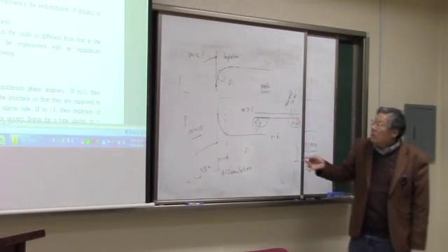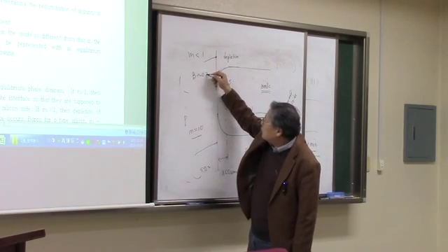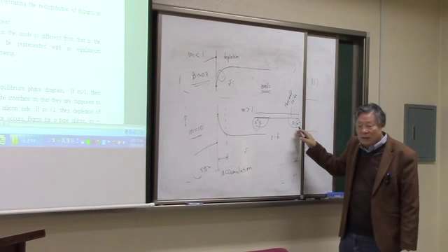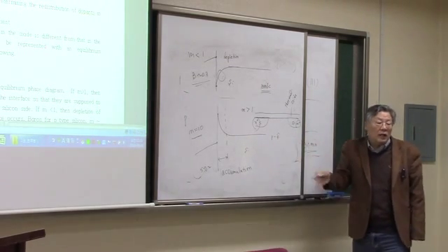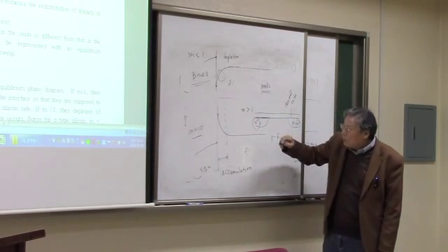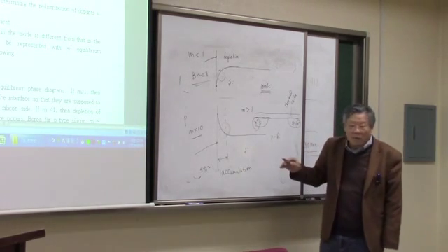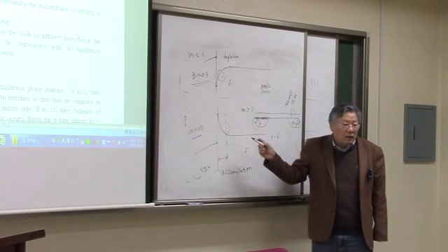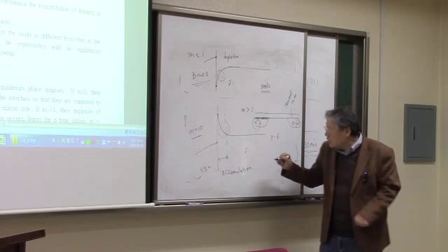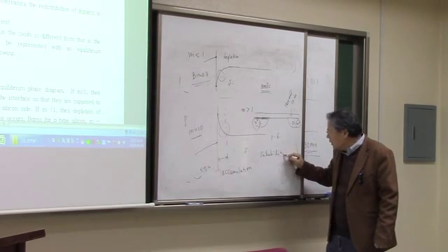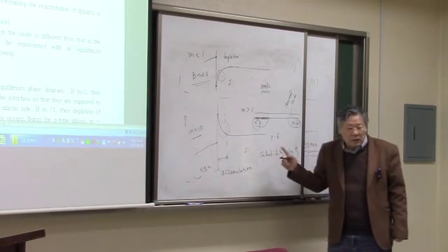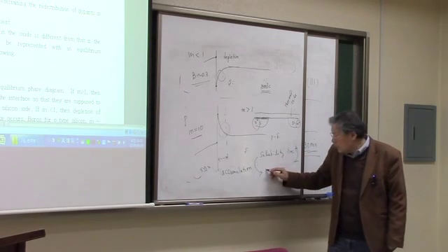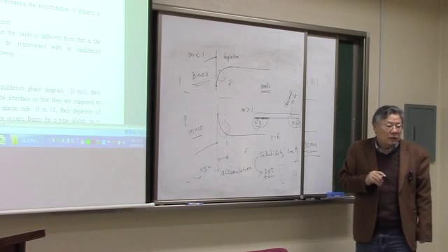It's much greater than 1. In the boron case, the M value is about 0.3. It's less than 1. So if you have a phosphorus doped area like this, locally, and then you grow thermal oxide in a later process, then at this interface you're going to have accumulation of the phosphorus at the silicon interface, right? What happens if you have an accumulation like this? Then this accumulation may exceed the solubility limit of phosphorus in the silicon, which will cause the formation of precipitation, the second phase of the silicon.